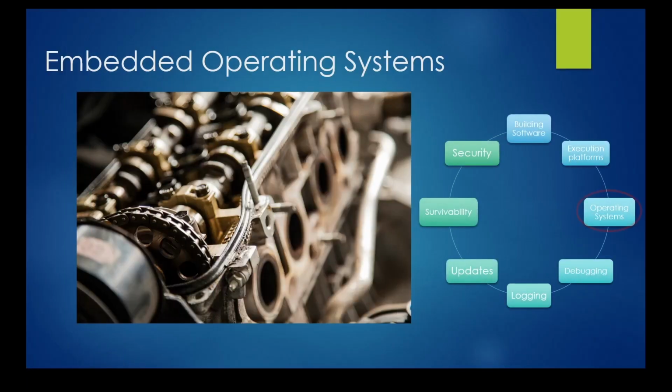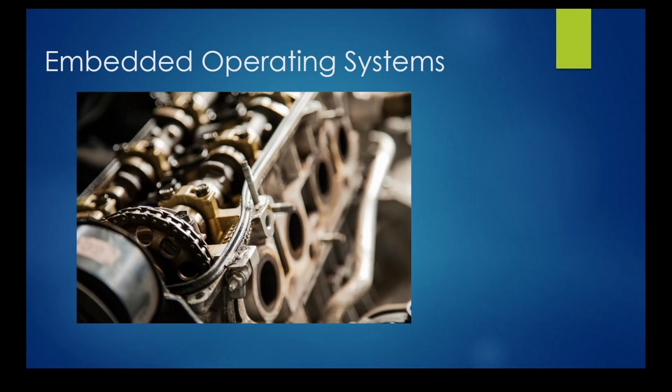We have built our firmware and we have executed it, perhaps even pre-silicon. Will our firmware include an operating system? Operating systems can give benefits ranging from scheduling threads to file systems and security features. Some embedded systems are simple enough to not require an operating system and can do with something similar to an Arduino loop, some interrupt handlers, and that's about it.